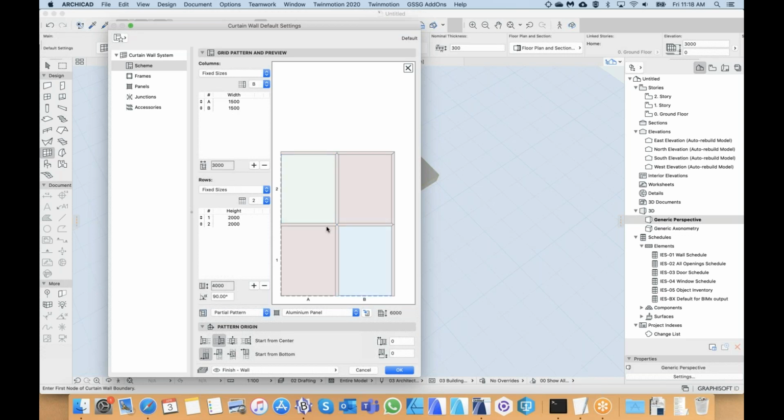And we want to get rid of all of these frames in the center. So we want to actually create all those as just divisions. What I'm going to do is select a frame. So I'm going to select one frame, and then I'm going to say all row, all across, and I'm going to change them to divisions because I actually don't want any frames. I just want lines between the panels. And my horizontal ones, I'm going to choose all above, all across, and change these also to division. So you can just select them individually by holding Shift. Yeah, and then making sure they're all set to division.